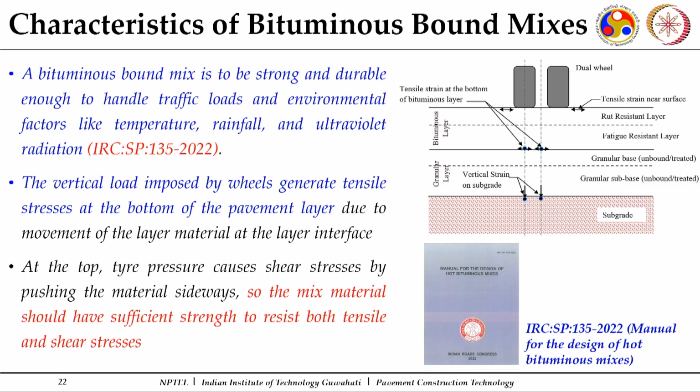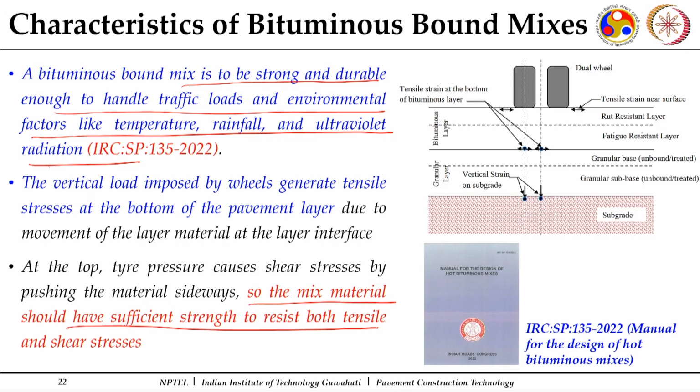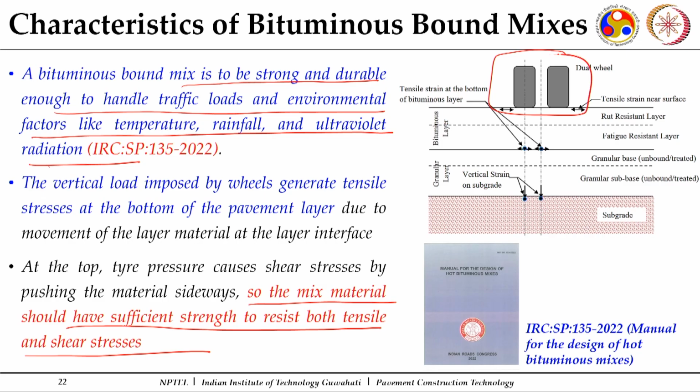These characteristics of the bituminous mixes are also used in the design of flexible pavements. It says that a bituminous bound mix is to be strong and durable enough to handle traffic loads and environmental factors like temperature, rainfall and ultraviolet radiation, which will occur during its service life. The mix material should have sufficient strength to resist both tensile and shear stresses, because there will be some deflection. Tensile stresses will generate, and there will be compressive stresses as well as shear stresses generated when the traffic load comes over the surface.